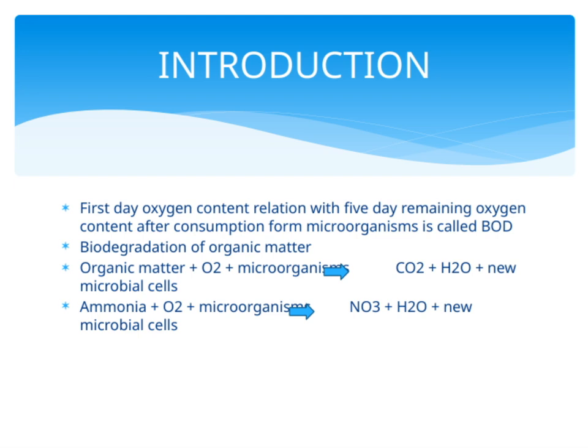Let's start by understanding what BOD, or biochemical oxygen demand, really is. It measures the relation between the initial oxygen content on the first day and the remaining oxygen after 5 days of microbial activity. Essentially, it tells us how much oxygen microorganisms consume to break down organic matter in water. This process is called biodegradation of organic matter, and it involves microorganisms breaking down organic compounds. When organic matter interacts with oxygen and these microorganisms, the end products are carbon dioxide, water, and new microbial cells that have grown and reproduced.